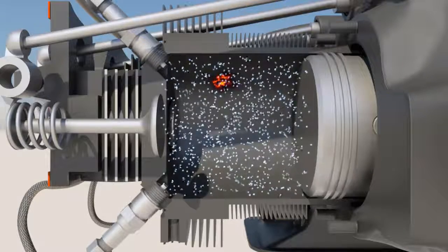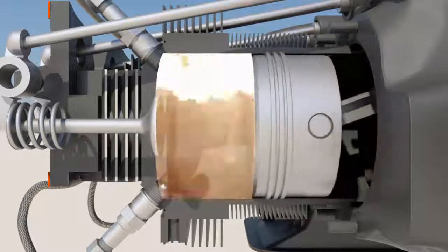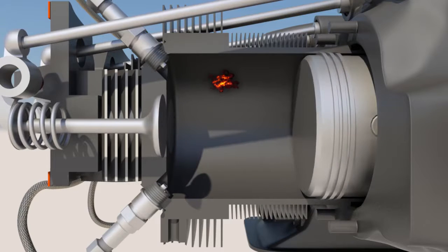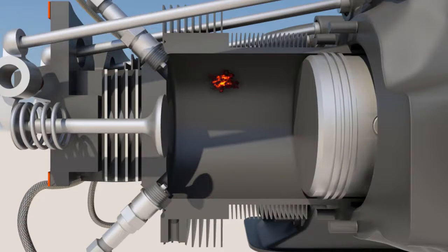Just as you'd expect, pre-ignition is simply when the fuel-air mixture is ignited prior to its normal time. This phenomenon usually occurs because of a lingering hot spot on the cylinder wall, usually caused by a carbon deposit that is hot enough to ignite the fuel-air mixture.